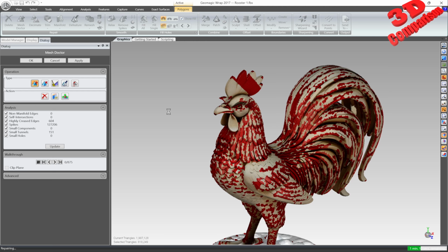It's important that we fix those, especially if you want to take this further within CAD. If you just want it as a simple 3D print, that's not a problem. You can just output it, load it in, and have that 3D print created. But usually it's a good idea to fix this if you want to further process the model within a CAD solution. So maybe within this video, I'm not going to go ahead and process all the models, but I'm really curious if there are any non-manifolds, self-intersections, or holes within the models.